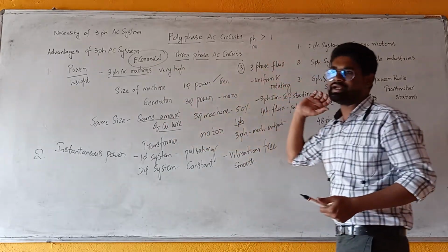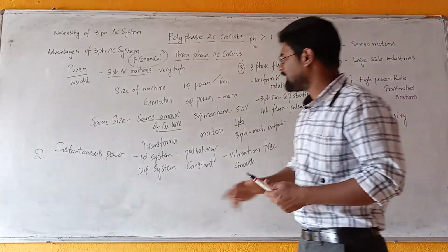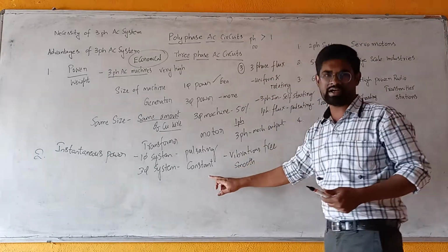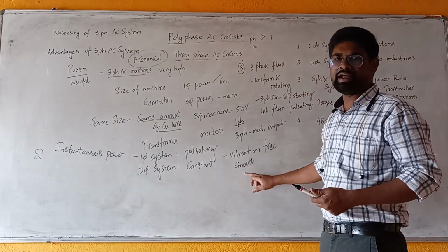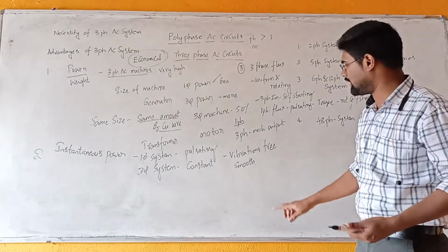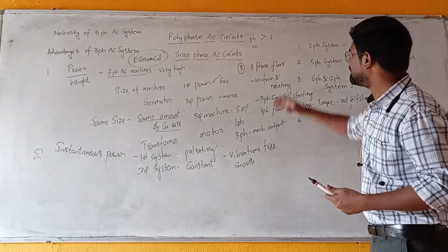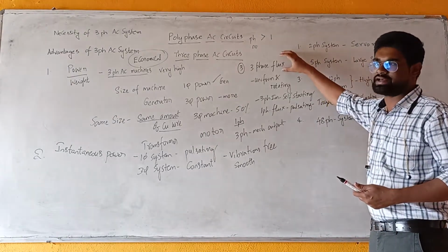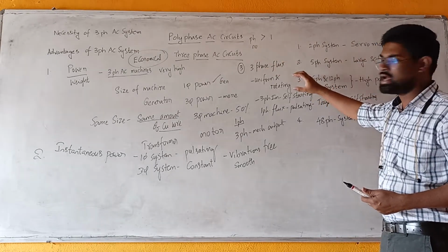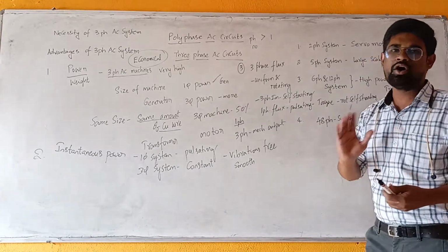And the second important advantage of the three phase AC system is that the instantaneous power of the three phase AC system is constant, so the operation of three phase machines, transformers, generators, motors is vibration free and the operation is smooth. And the third important reason is that the three phase flux produced from three phase supply is uniform and rotating, and the three phase induction motors are self-starting and better in operation.